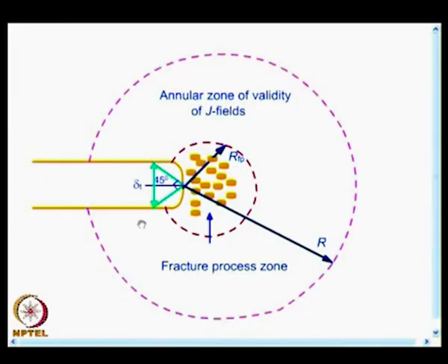Within the crack tip you find some lines drawn. If you look from the center, you have lines drawn at 45 degrees, they are mutually perpendicular, they hit the crack, and this height is taken as delta t. We would see this when we look at what CTOD is, and what is represented here is the crack tip opening displacement. Once you come to EPFM, these concepts go together.